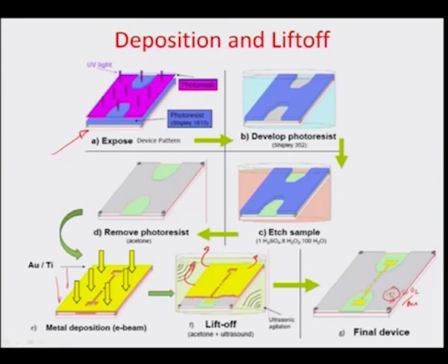So, wherever there is a bare SiO2 which was exposed, in this crevice here or in this crevice here, the gold stayed and it basically developed a bondage. The remaining film, even if it went off because of development, did not allow this portion of the film which was in that open area, that crevice area, to go away. So, that is how you actually realize microelectronic prints or circuits, by using deposition and lift off.